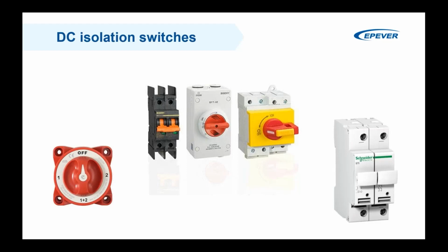Normally we isolate the positive battery cable, as I mentioned, but it really depends on your local standards and regulations. And these also have a voltage and current rating. It's important that you check the product labeling for how much current and how much voltage this can tolerate, and it should be in range of your requirements.